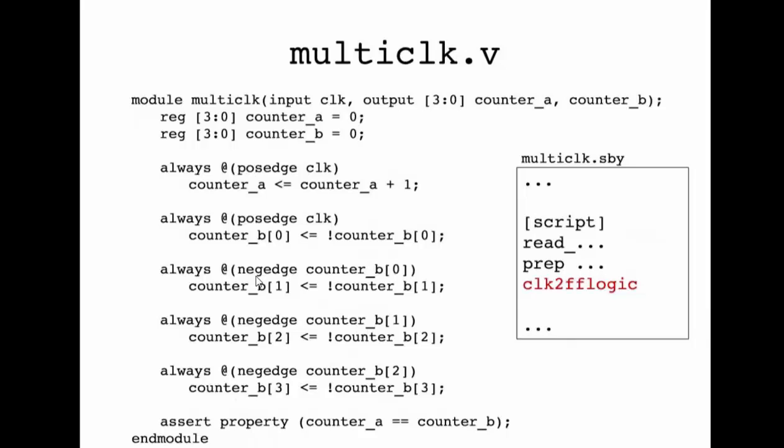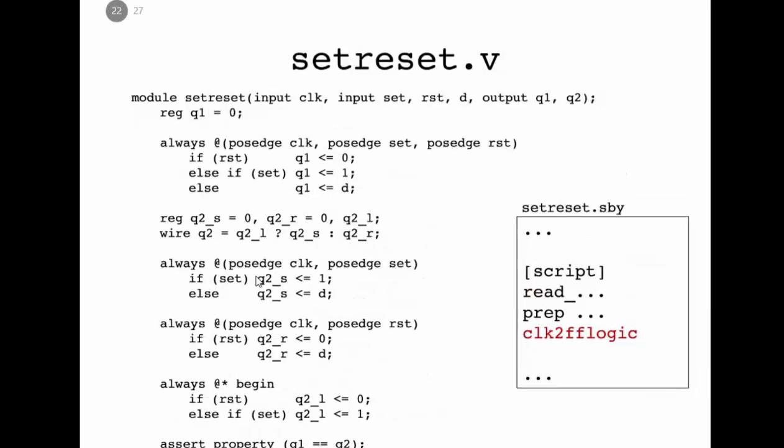So of course, this will not perform anything like static timing. So there are still other things to verify about this kind of counter. But if we are thinking about our design in the same terms that Verilog simulation would think about it, that clocks trigger instantaneous events, stuff like that, then we can prove that these two counters are the same. And we can also model things like asynchronous sets and resets here.